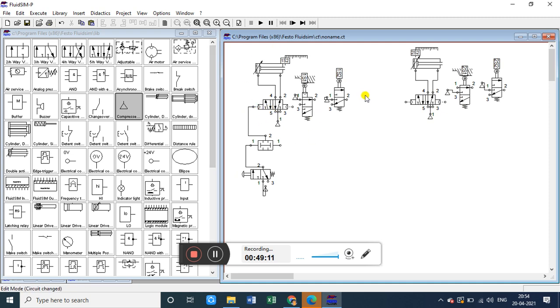Now what is the initial condition? You can take a reference of the pneumatic circuit diagram for the A plus, B plus, A minus, B minus sequence of the process. B minus is the last process. B minus means the rod end has to come to the 2s1 position. So what I will do, I will take this and connect over here. This valve has input from the 2s1 limit switch and one manual push button, a 3 by 2 valve. Then it will come to this side.